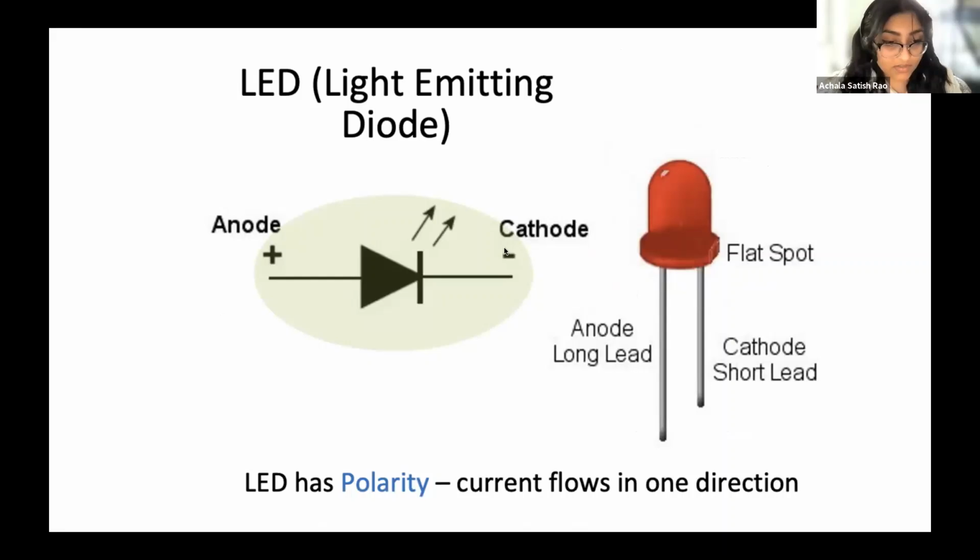So in terms of connecting your circuit, there's polarity to certain objects. For example, your LED. You can't just wire either lead of the LED to any side. There's a positive side and a negative side. Usually the anode, or the positive side, has a longer lead and the cathode has a shorter lead.